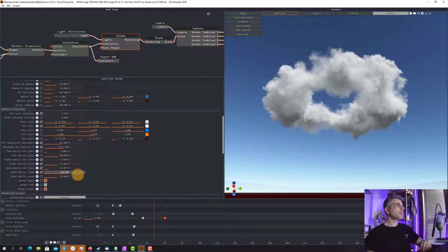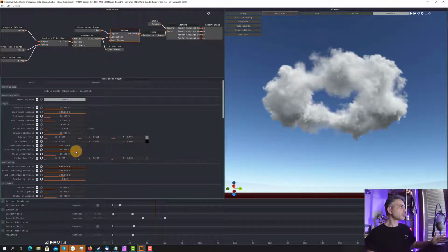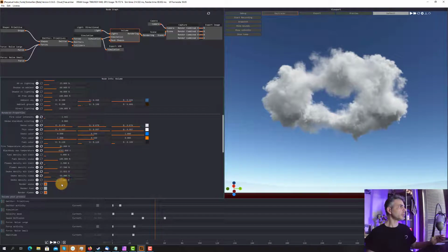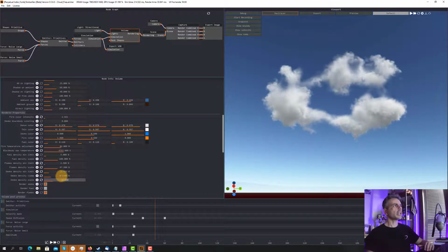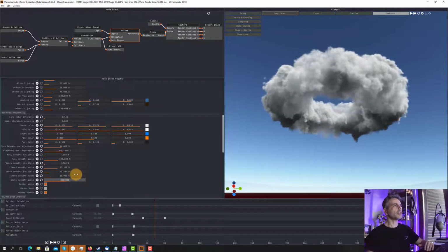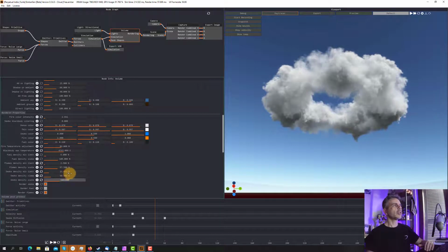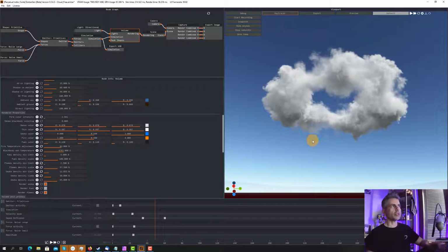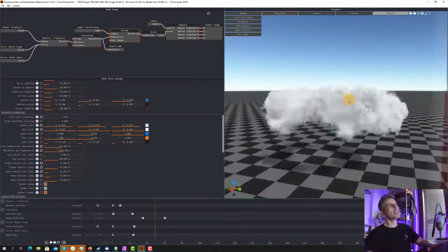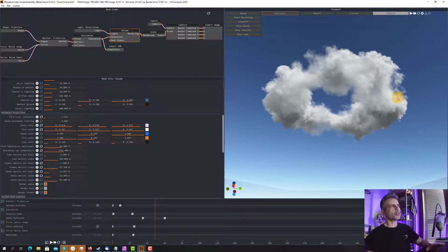I think you can play, we have something like that also in the other software, so we can use it. For example, we have the possibility in other software to decide which is the minimum density we like to use. So we can achieve something like that also in the other software. This is the smoke density multiplier, so you can change how much density we have. So you see we have more deeply control over the density and the final look for our cloud. I like to have the default value, 95, is nice enough. We have a nice level of detail, we have wispy clouds, we have high density with shadows, gray shadows, so I mean, it is perfect for me.